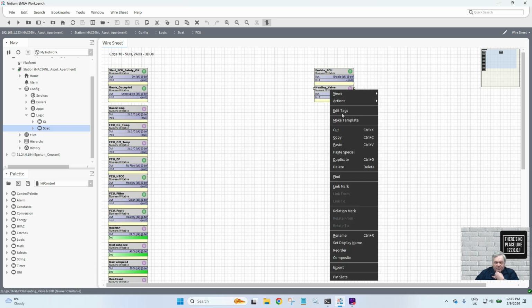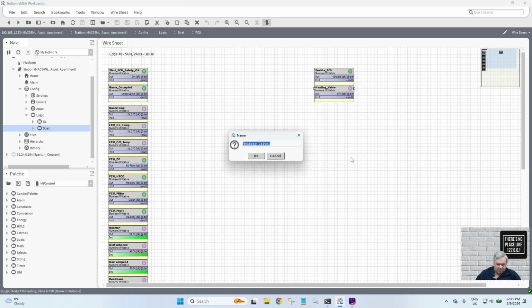And then of course we've got a cooling valve. If it's a 4-port, if it's just a 2-port, then it can either be, I've seen 2-port fan coils on the perimeter of a glazed building, and it's just got a cooling coil because of the thermal gain, and I've seen them also just have a heating coil, but I've also seen them have the heating and cooling coils as well.